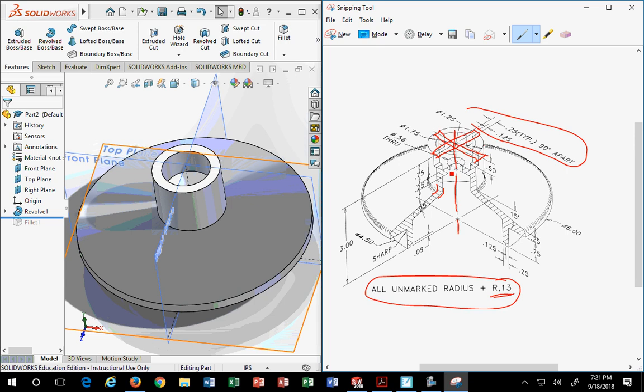Now, my machinist, would you just drop the depth, or would you mill across down to the depth? Or would you just go through the side wall? Probably mill down. You'd probably mill it before you put that hole in it, I imagine, right? Mill the slot in before you put the hole in, before you even put this interior hole in. This would be a next operation.